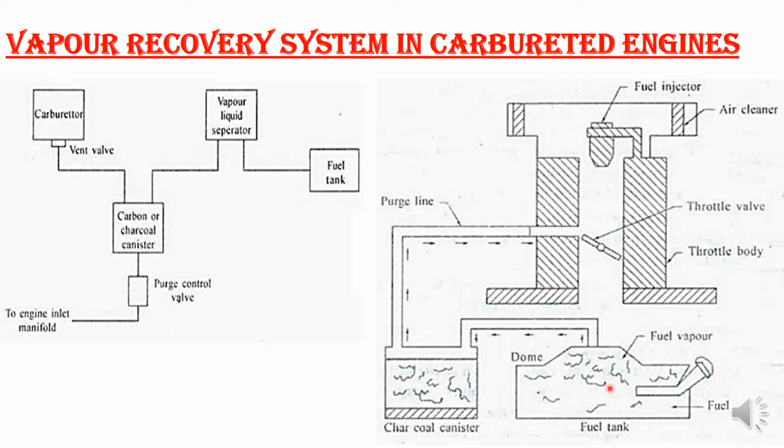The fuel tank breathes with the change in temperature. As the temperature increases, the air inside the tank expands and is forced through either the filler cap or the vent tube. This air carries the gasoline vapor. When the temperature decreases, the air inside contracts and outside air comes into the tank. This breathing of the tank causes loss of gasoline vapor, discharging it into the atmosphere.